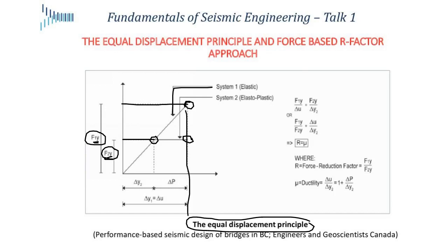Okay, so I say, well, how can I design this intelligently, have some controlled, contained damage, but make sure that my structure behaves properly? What you really need to do is have your structure so that it's able to get to this displacement level. And that's why I was emphasizing the point that an earthquake is really a displacement demand. So if I reduce the strength of the structure, I only design it for F2y, now as long as I meet this displacement demand, I'm going to be okay.